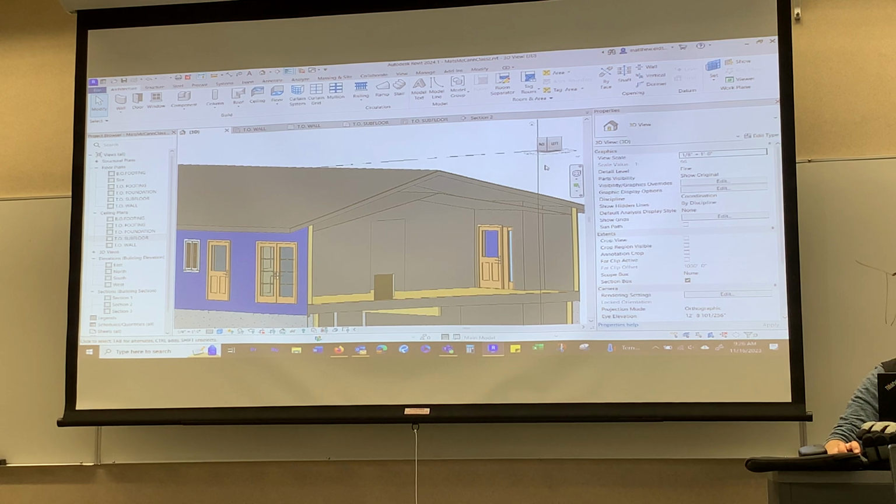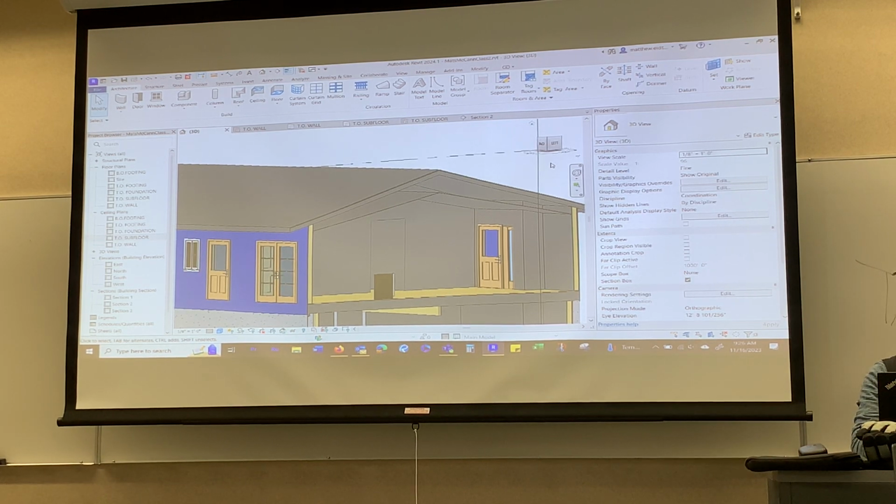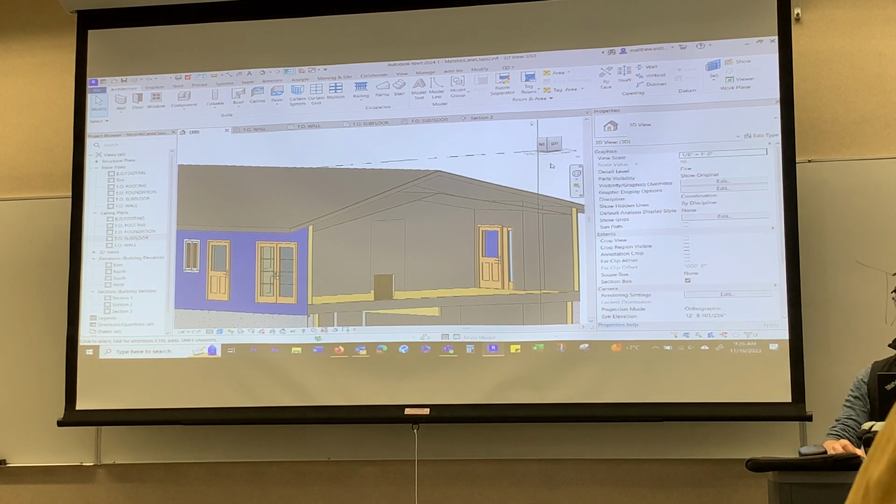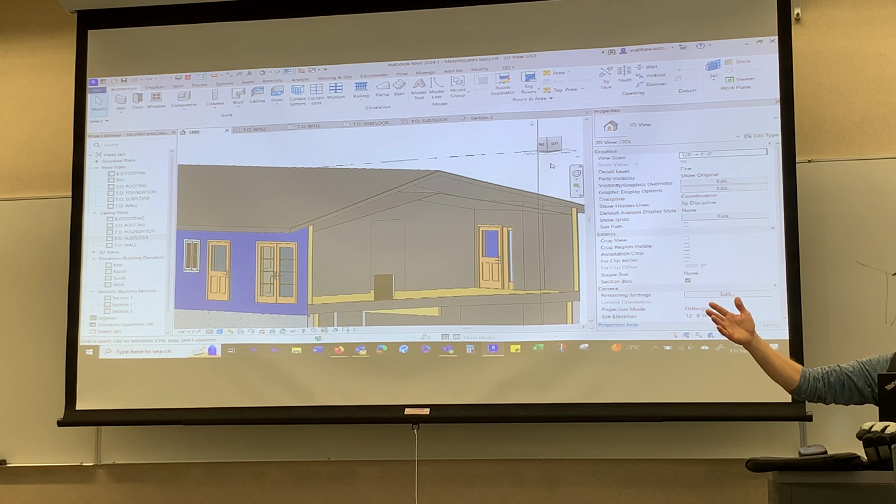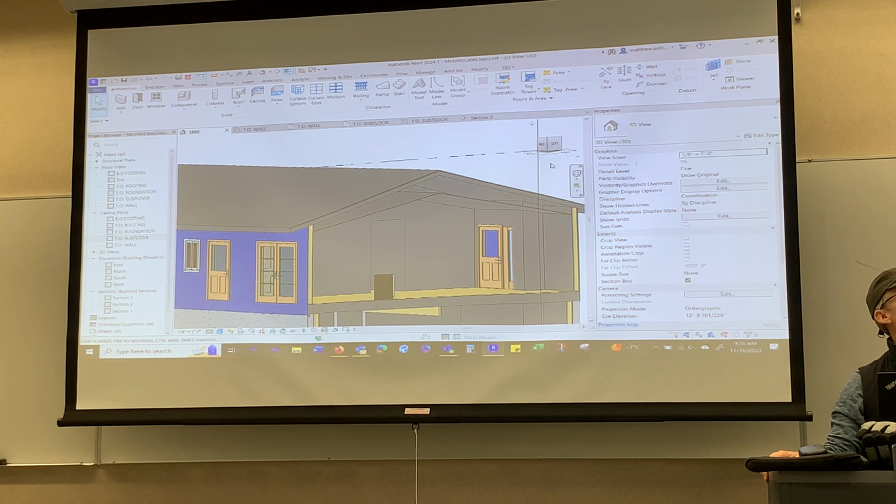Because the steps, I mean, I wrote them out, but the constraints are there, and set the constraints as shown in the figure above. Repeat to the other side, you just need to notch out the front wall recess. Use this foot element. I used a rectangle in the steps at step 24. I used the rectangle tool on it, and then I trimmed it with that split. Rather than using a rectangle like I just demonstrated, you can use the pick lines tool, or obviously the rectangle tool and just cut it out. Either or. Step 24 is different than how I did it, but there's more than one way to skin a cat, as they say.